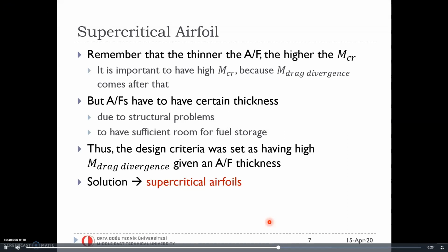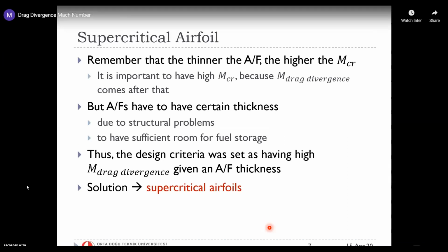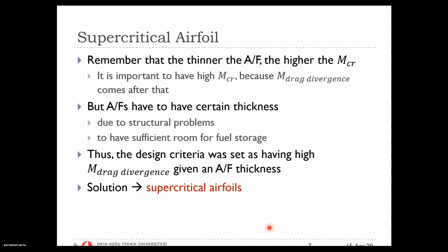This critical Mach number, and I told you that thinner airfoils have higher critical Mach numbers. However, there are also some other aspects that you need to take into account while designing an aircraft. You cannot make the airfoil infinitely thin and expect that it will still operate at the given flight conditions, because you need to consider the structure. Is it rigid enough, or do you also need some space for storage or fuel? So you cannot make the airfoil too thin.